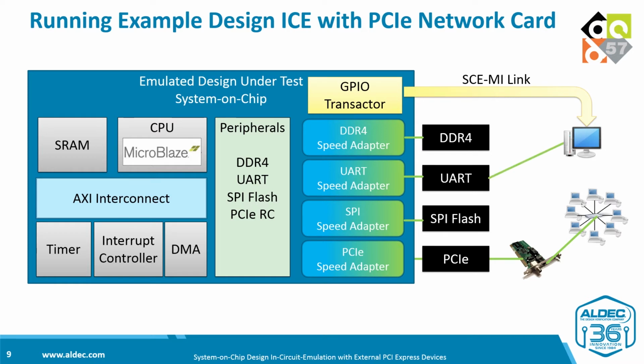That's why UART is connected to the same host workstation, and I can observe the embedded Linux terminal. The host workstation is connected with the network, so I can close the testing loop with the PCIe channel.